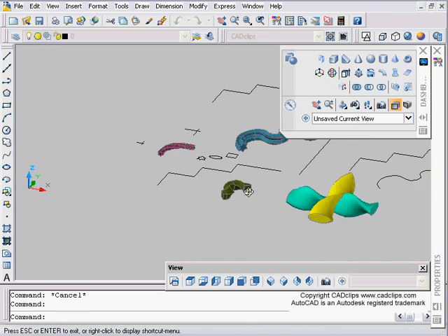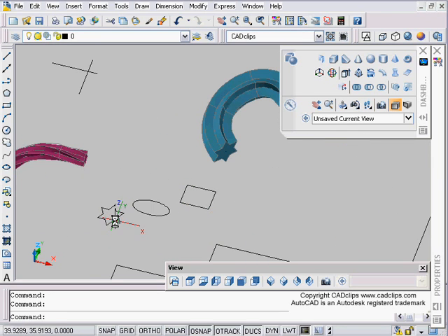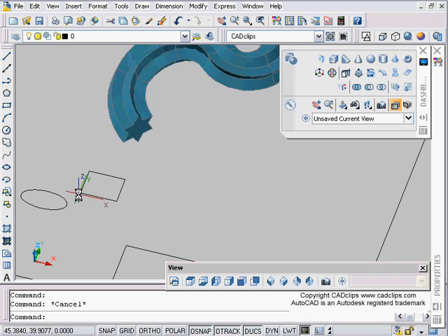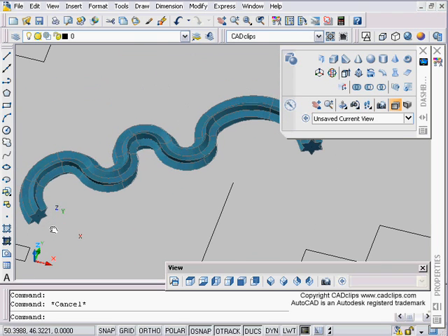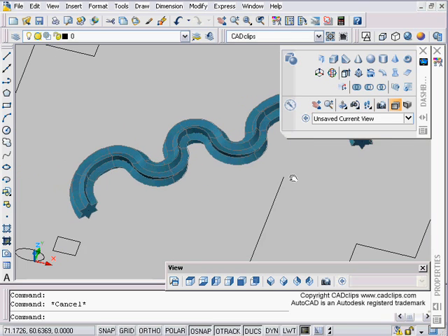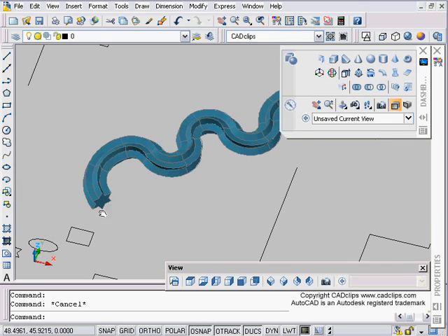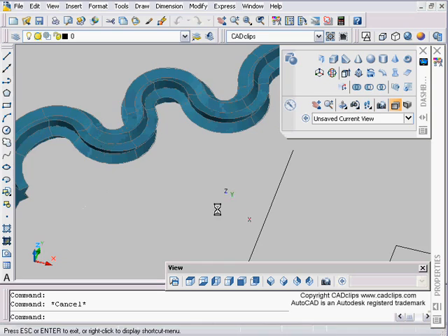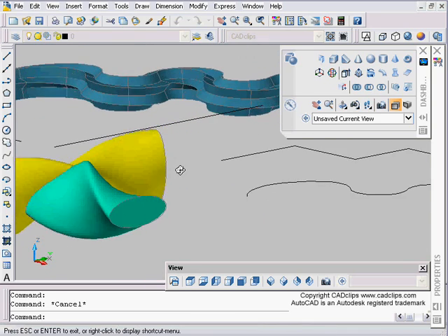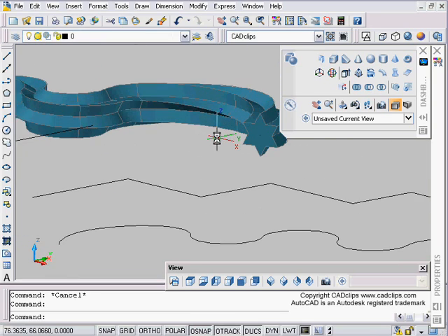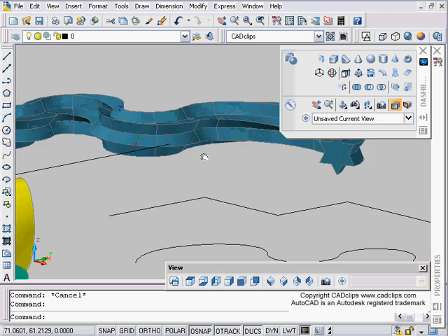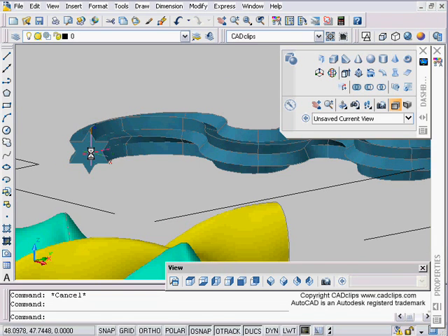Here's another example before we get started, where I've taken a shape like a star, just a polyline. Then I've taken another polyline that has been fit curved, and I take that star and sweep it around there, and in this case I also gave it a slight twist, I think a 30-degree twist from start to end.